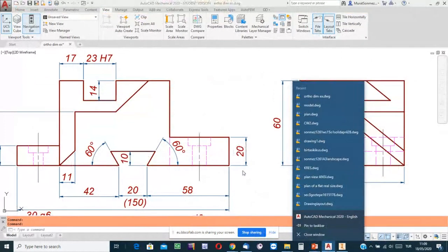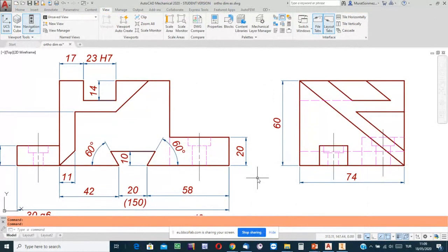here 20? Nobody can measure the distance as exactly whether to check it is exact, because we have no such instrument yet. The other reason is that the size of any feature cannot be set precisely equal to a certain specific value, because during the manufacturing stage it is impossible to avoid background noise, background oscillation, shaking effect in the building, in the structure. It will also shake the cutting tool, so exactly equal is impossible.